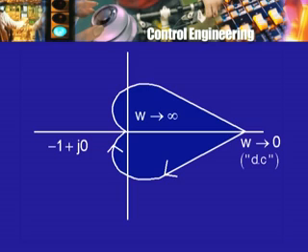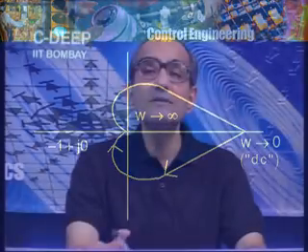And of course, I will show them both as actually passing through the origin, although in practice they will not come to the origin because of the argument earlier, that in this case the number of poles is 2, the number of zeros is 1, therefore, the image of the semicircular part of the Nyquist contour will be essentially very close to the origin.